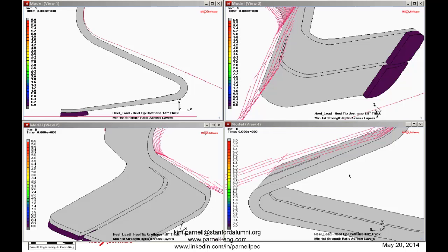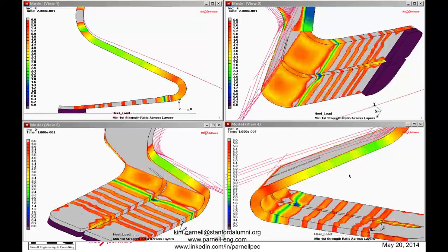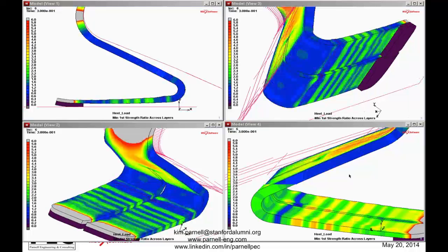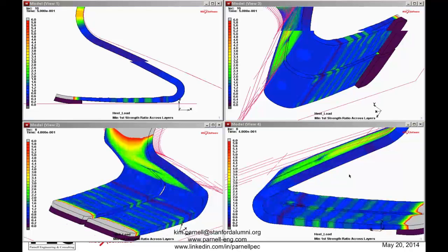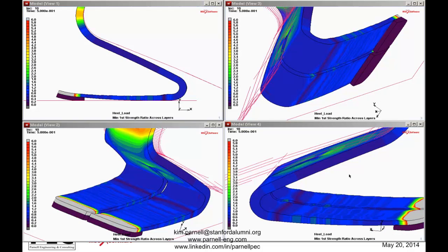These are all views now of the short urethane pad as we progressively step through, progressively increasing the vertical displacement, and how you make contact with the pad, how you make contact with the composite heel component, and then there's another contact here with the surface of the keel.